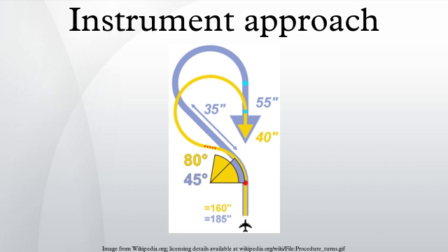Simultaneous close parallel approaches. At some airports, multiple parallel runways are available for operations, but are so closely spaced that they present a hazard for simultaneous use under ordinary conditions. Simultaneous operations on such runways can be carried out using ILS and special precision runway monitor radars and 3 controllers, with special procedures known as simultaneous close parallel approaches. In this type of approach, 2 aircraft approach and land simultaneously on closely spaced parallel runways, with extra air traffic controllers assigned to monitor each approach path on special PRM radar.